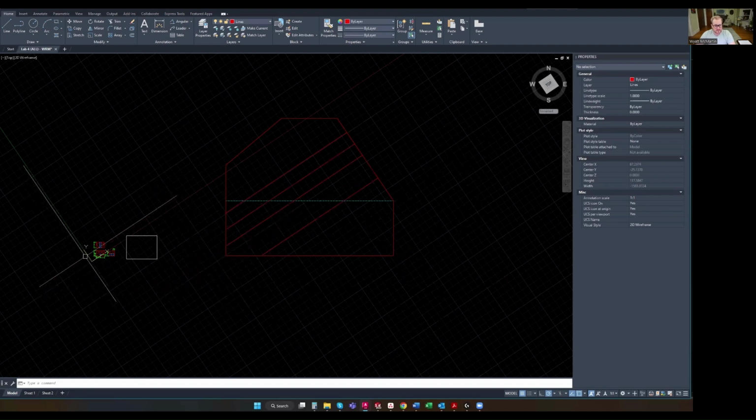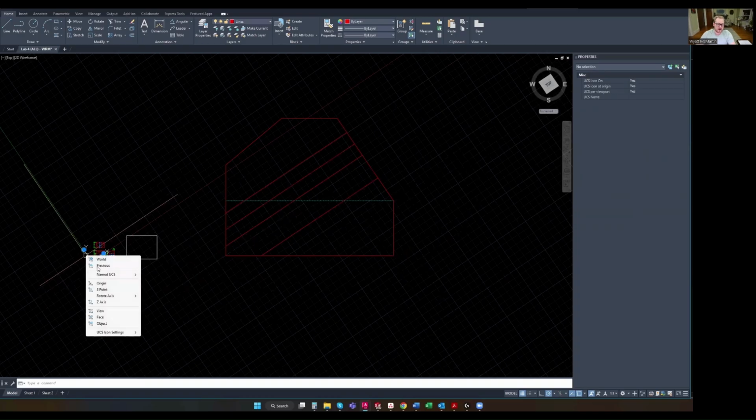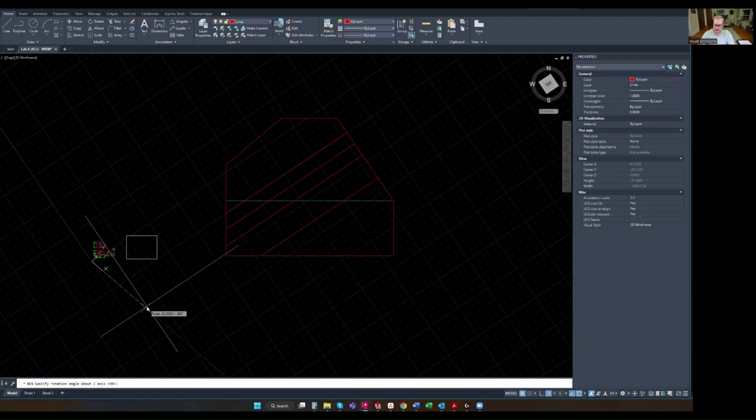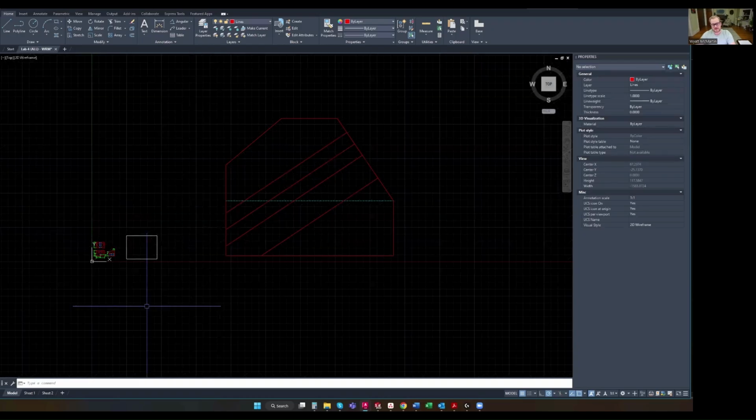So from here, select the UCS again. So just left click on it, then right click, rotate around the Z, and we're going to type -34, enter. And that is going to get your grid back to 0. So now when we use a line tool, 0 should snap as normal. With that, let's go ahead and turn off the grid.